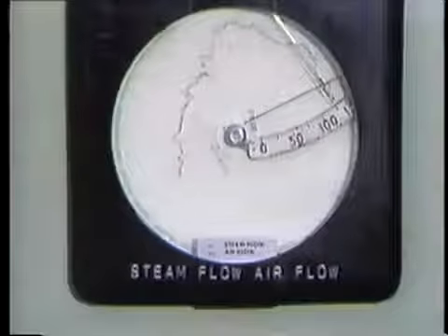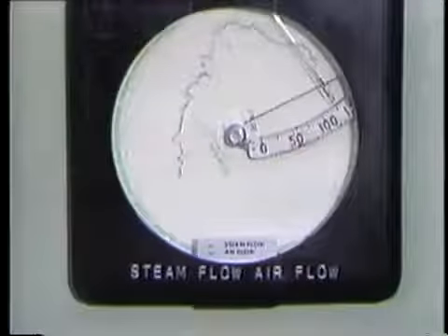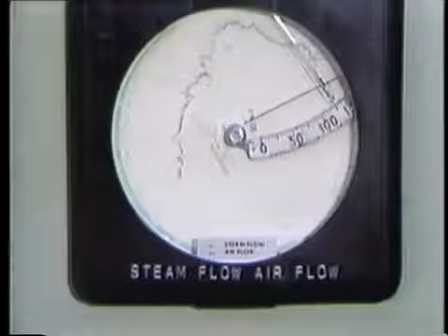What you can do to keep explosive situations from developing is to carefully monitor your boiler flame and to make sure that combustion is taking place properly. You should also keep a careful watch on the fuel flow and airflow to the burners to make certain that both are being supplied in proper proportions.